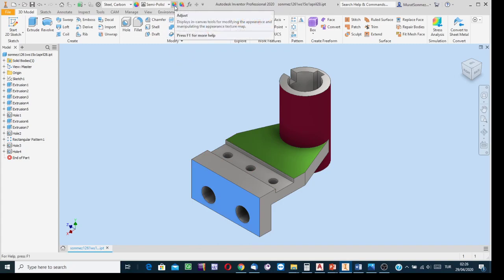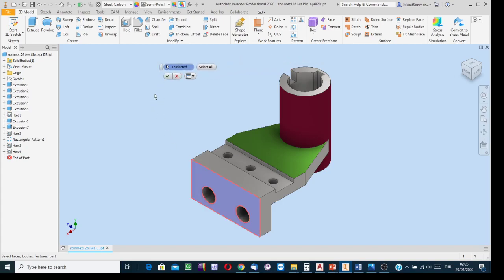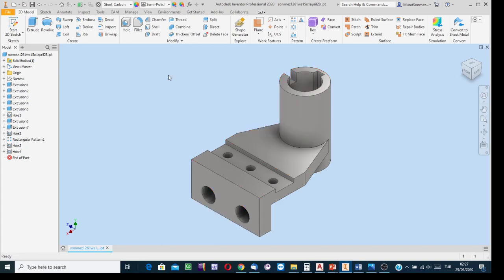Next to this tool, there is one more button. It is like a pie chart, but here there is a cross on it. It is the tool to remove the paint. Select the surface with a click, and then click on the OK button. But if not only for this one, but from all the already painted surfaces the paint is to be removed, select the all button, and then say OK. Then all the paint will be removed from the surfaces.